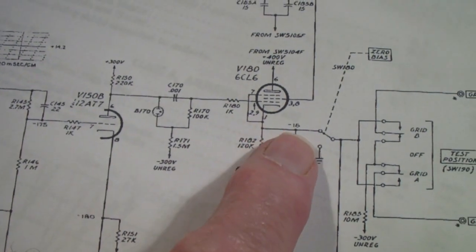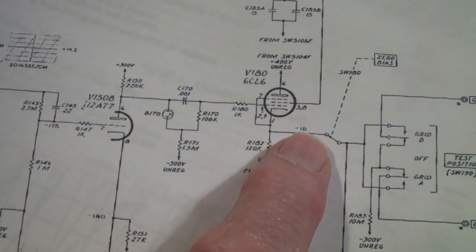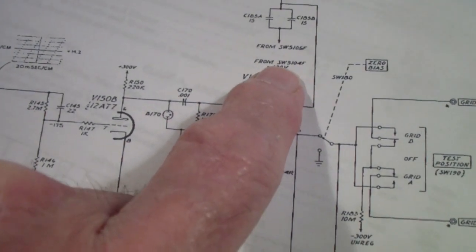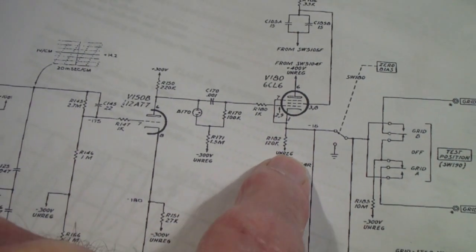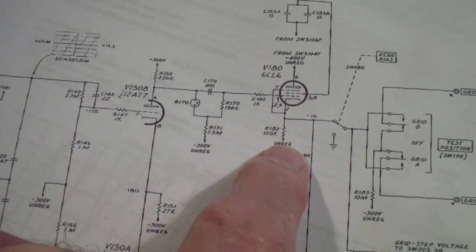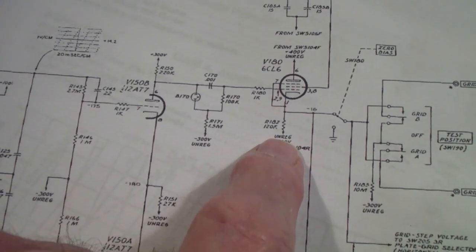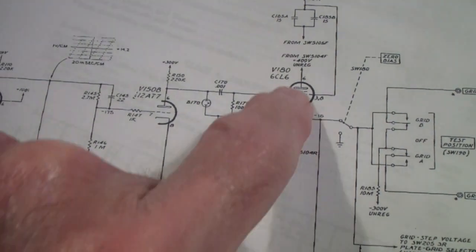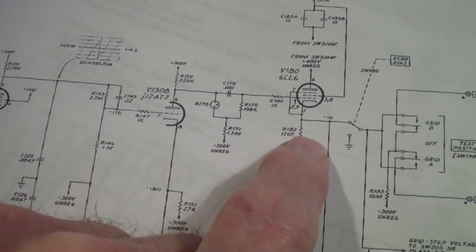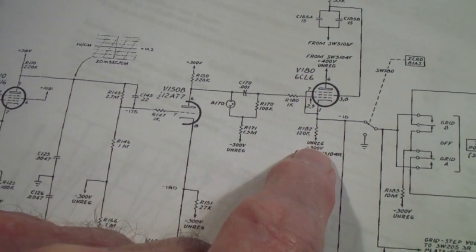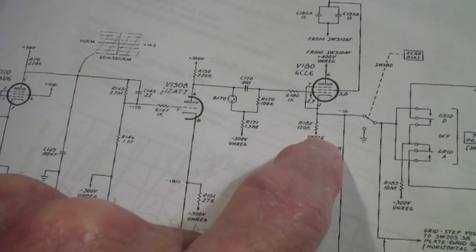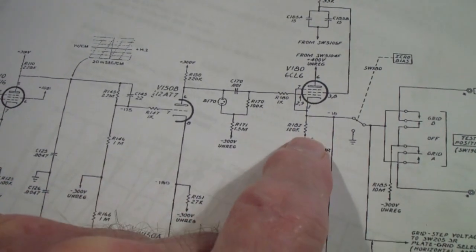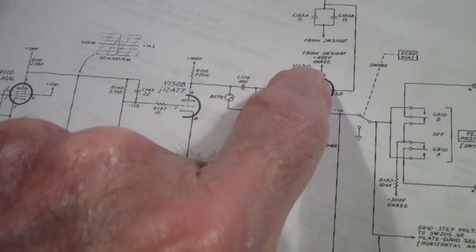So why did I do that, and what was my theory in adding those capacitors? Well, what those do is they clean up these power supplies, and I think what is going on is the leads, that is the wires, from these two terminal points, which are in that area that I showed you a minute ago where the capacitors are located, that run all the way back to the power supply, are rather long. In fact, they're about 4 feet long by my calculation. And here's one of the reasons I think that causes a problem and why they need to be bypassed right here, right at the tube.